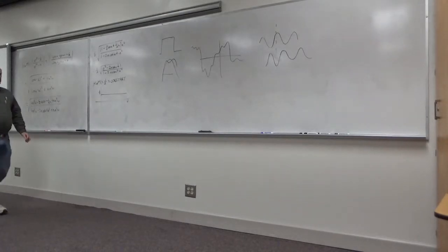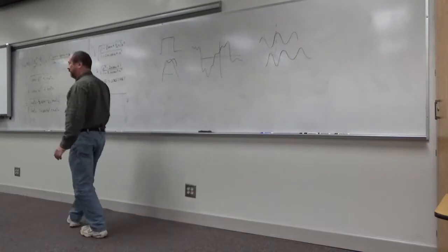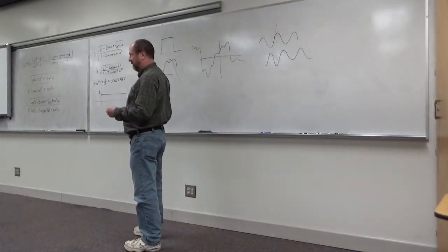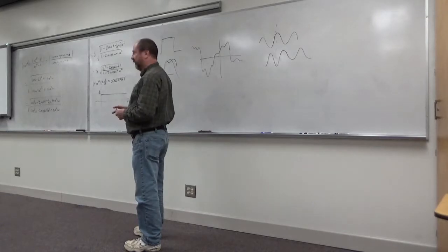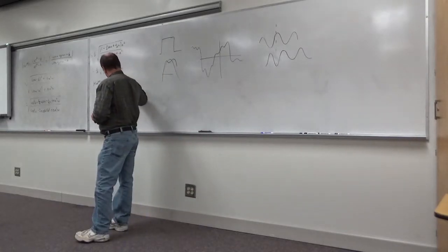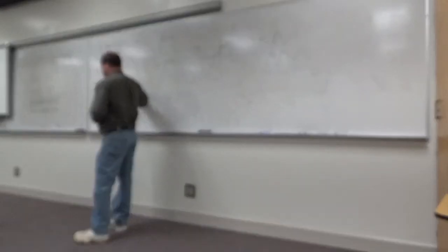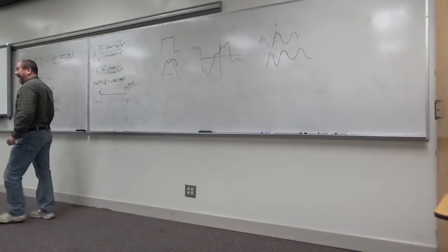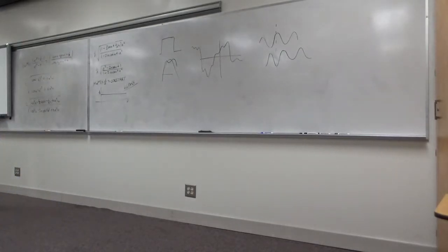What kind of a filter? This is the kind of filter we don't talk about much. You've got low pass, you've got high pass, you've got band pass, you've got band stop. What is this? It's what's called all pass. Okay? In other words, what does it do? Whatever the amplitude of the input sinusoid is, comes out with the same amplitude.